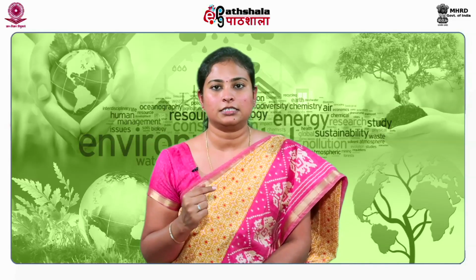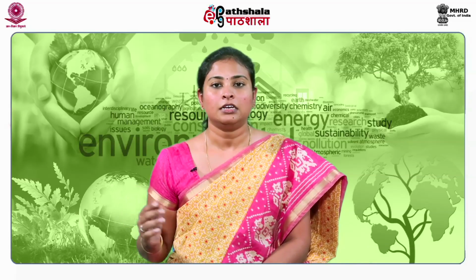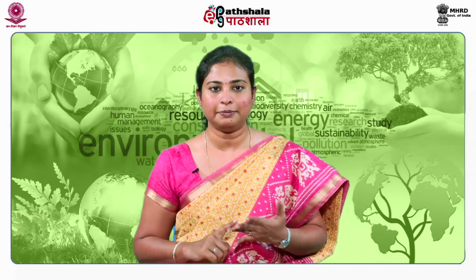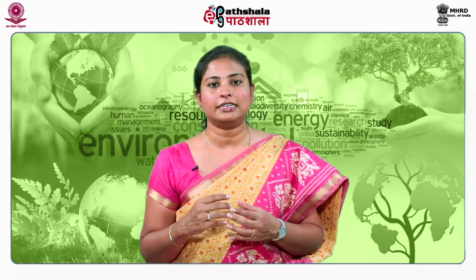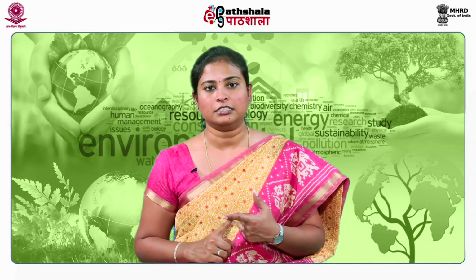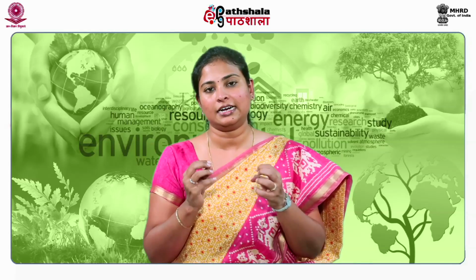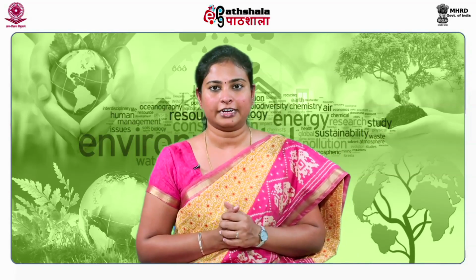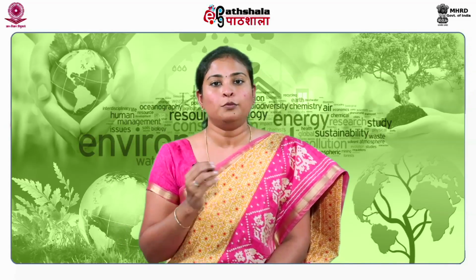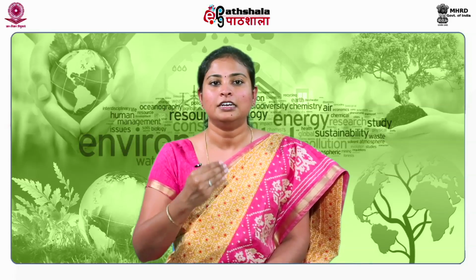An ideal gas collection system consists of a sequence of gas collection wells which are positioned throughout the landfill. The gas collection wells will be designed based on the volume and density of waste, and the depth and area of the landfill. Collection wells in the landfill offer pathways for the passage of gas. The gas collection system is very important because if it does not work properly, an explosion can occur within the bioreactor. You can also see more gas generation in the early phase of operation. Moreover, when compared to conventional landfills, landfill bioreactors generate a high amount of gas.